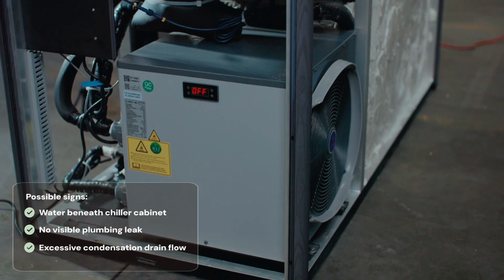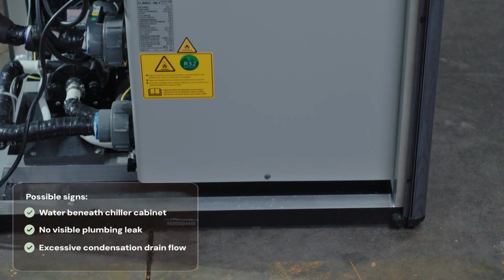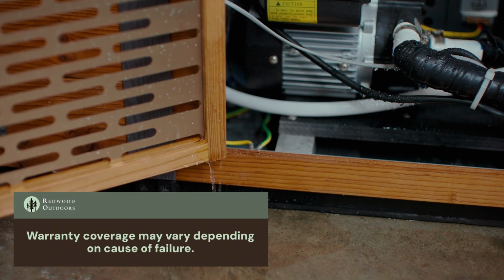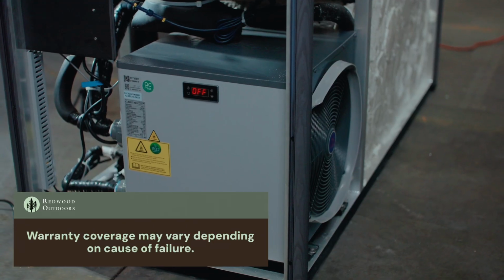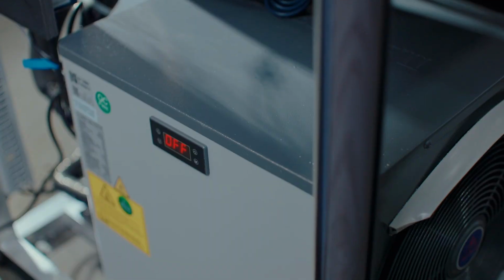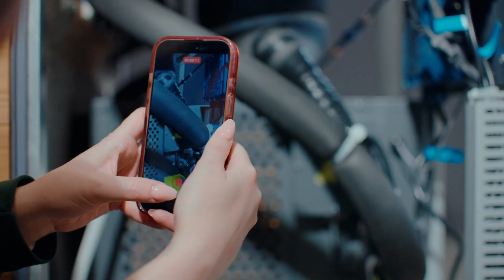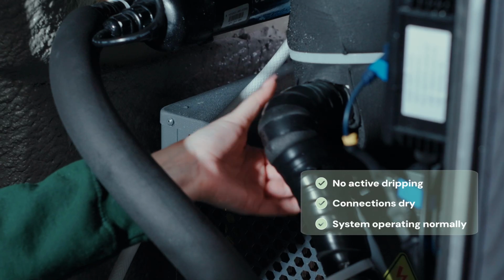The Balboa Chiller housing should generally not be opened during standard field diagnosis unless specifically directed by Redwood Outdoors Support. If the leak is confirmed to originate from inside the Balboa Chiller assembly, the complete chiller unit will typically require replacement rather than repair. Warranty eligibility may vary depending on factors such as freeze damage, maintenance history, unit age, and overall system condition. Before reinstalling the exterior panels, refill the tub and test the repaired area for leaks.